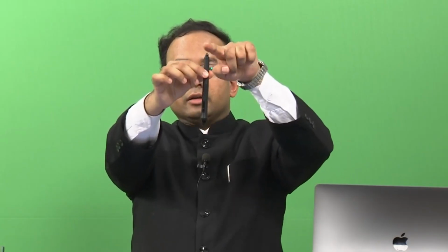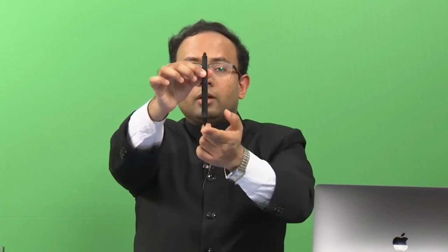So, you will keep it like this, and you will place it in such a manner that you are seeing the top of the hypsometer and the top of the tree, and you align your hypsometer in such a manner that both these points come together. And similarly, you move in such a way that the bottom of this hypsometer and the base of the tree are looking at the same point, from your perspective.